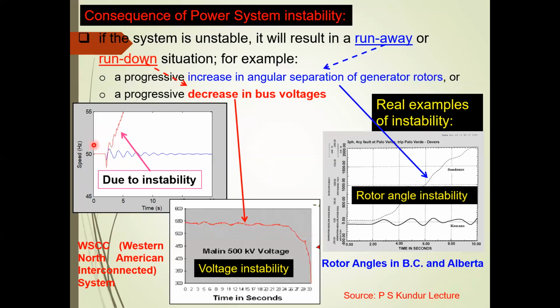Let's say you want to have an allowable limit of 2% frequency deviation in the system, for which the system remains in synchronism. So if you have a 2% change from 50 Hertz, either on the plus side or minus side, whenever this 2% change crosses the limit, then the relay will detect it.